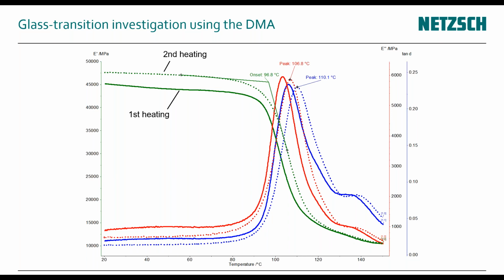You do a first heating, you cool down again, you do a second heating. If you see a shift of the glass transition temperature, this is a clear sign that you have post-process cure, or that you still have residual cure in your process. And it does not matter what type of matrix. I've not been talking about different resins and different fiber orientations and so on, because it's all the same signal that we see. And of course, this is very true for phenolic resin as well.